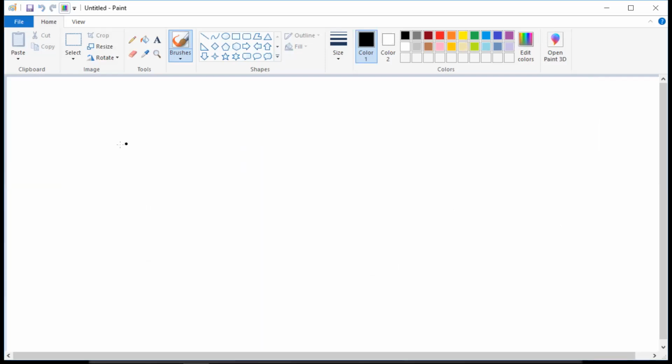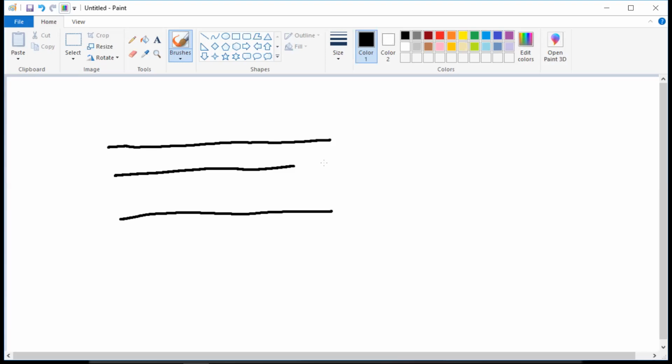Okay, I'm going to just draw a primary conductor here. The center core of it. This is where the voltage goes. And this is the insulation. You've got ground on the outside. We'll go more into that later. What happens here on an open of a primary conductor is it burns in two.